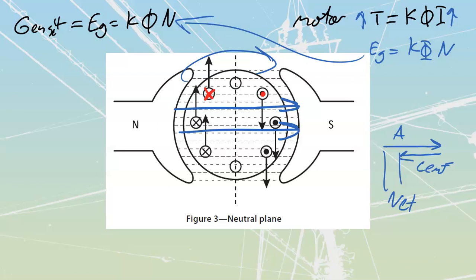Because this is really going to allow us to view another formula in the correct light. This next formula has a few more letters inside of it, but then we're going to be able to drop them down into something smaller, or simplify. I'm just using Ohm's law. Let's start by writing out this next formula over here. The next formula is my E armature is equal to my E applied minus my E generated.